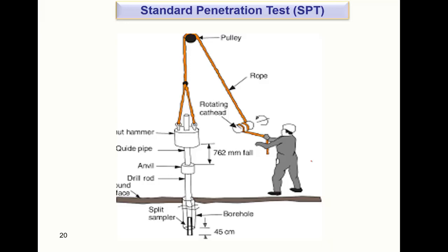For other samplers, we have other types of testing methods. We'll discuss them gradually, but today we'll discuss the standard penetration test, the SPT test. If you talk with engineers who deal with piling, soil testing, or making soil reports, they often use the SPT test.